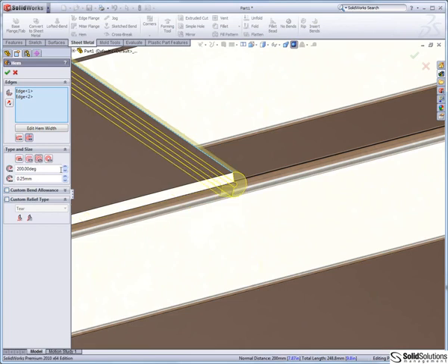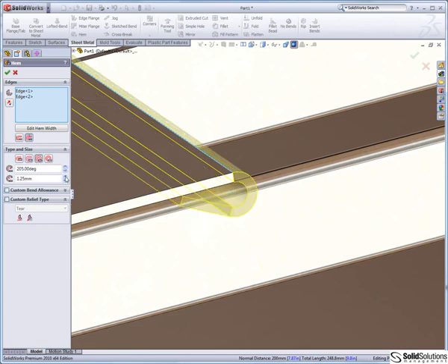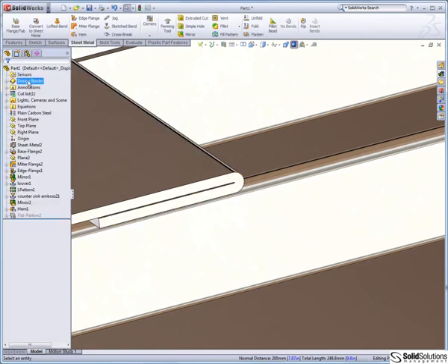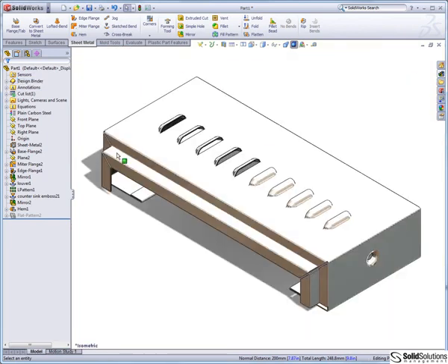for each option. So we've got a teardrop hem, a rolled hem for a sheet metal hinge, and we can change the amount that rolls around. In this case I'm just going to do a safety edge just by squashing the material down onto itself, just a closed hem.